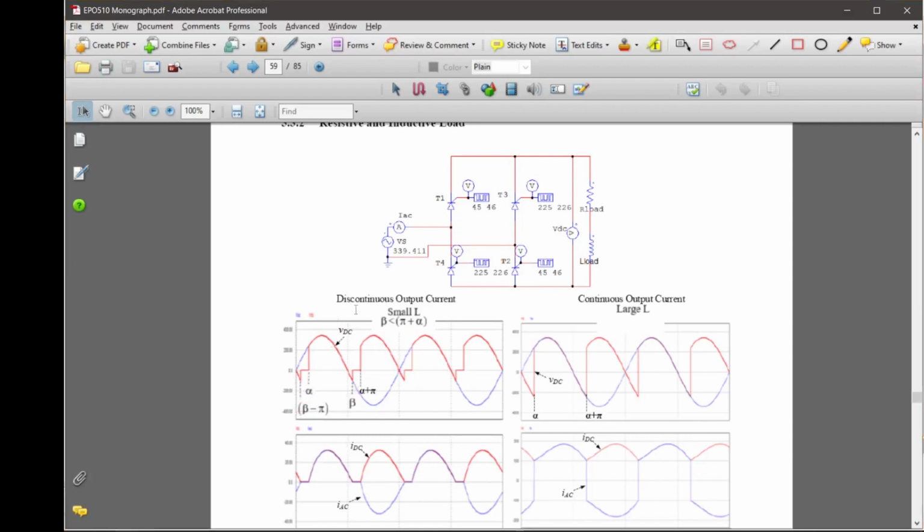At the beginning, let's say there is no current at all at the output. Of course you start with zero, everything reset to zero, current is zero, everything should be zero. So let's say this is flat, starting from zero, ignoring that at the beginning of the simulation, for example. So we start at 0 voltage here, output voltage equals 0. And then we trigger thyristor 1 and thyristor 2 at alpha, isn't it?